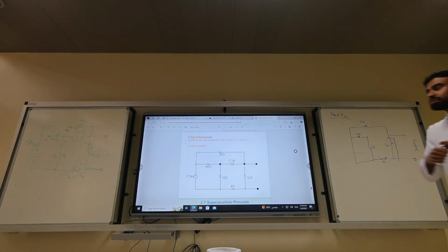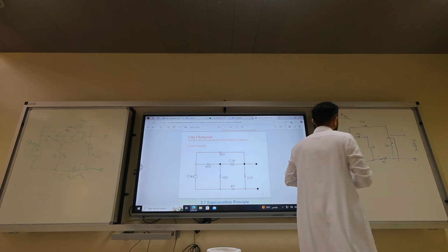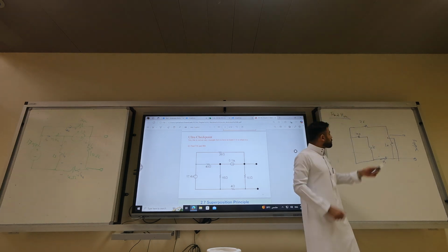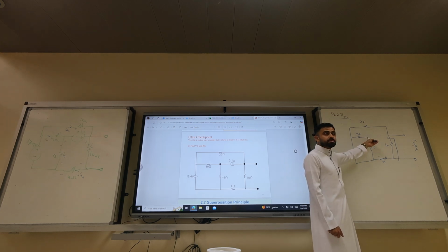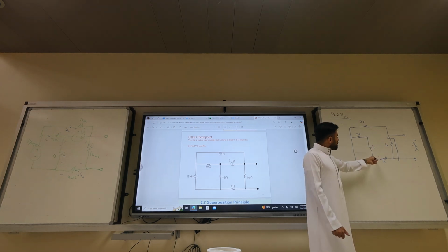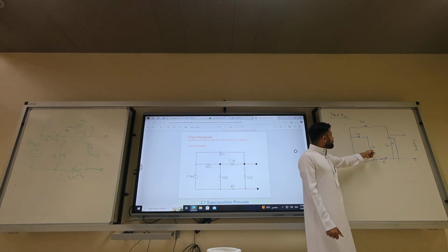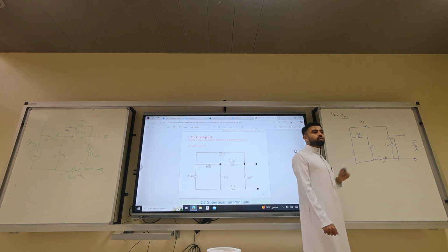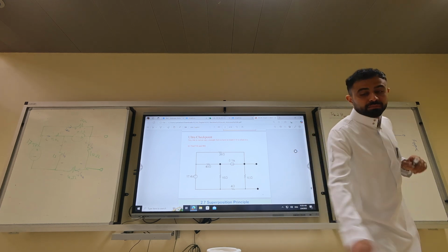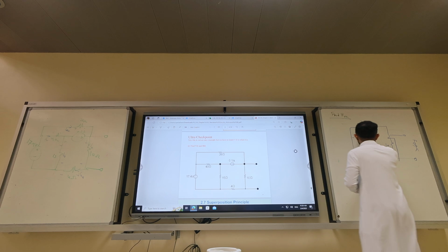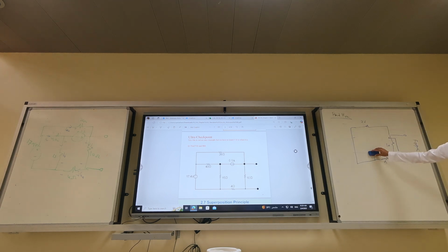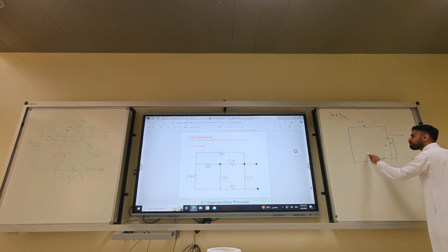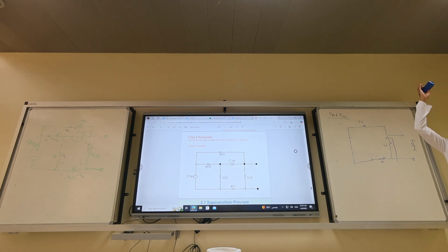A smart student will tell Thevenin, hey Thevenin, we have 15 and 40 in series. Why? Because nobody interferes with them in the middle. However, both terminals of the 15 and 40 are short-circuited. So what do we do? Kill them. Get rid of them. Don't distract yourself. They are not zero. They are the electrons. All the electrons will move here. None of the electrons will move across the resistor. So just delete them.